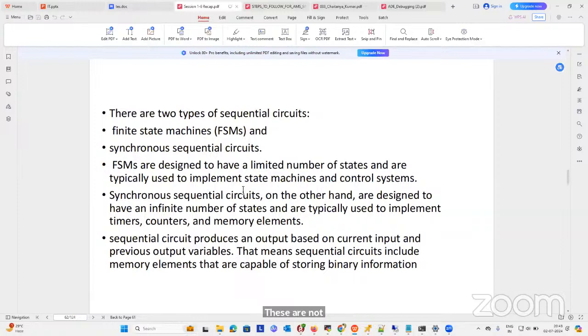And we have two sets of inputs. The current input is the outside person, and the previous input is the inside person. And the initial state we have to declare, in which floor it is, or we reset it to reach the ground floor or the top floor. Okay, this is how we design an FSM for an escalator or lift. Hope you got the example, right?